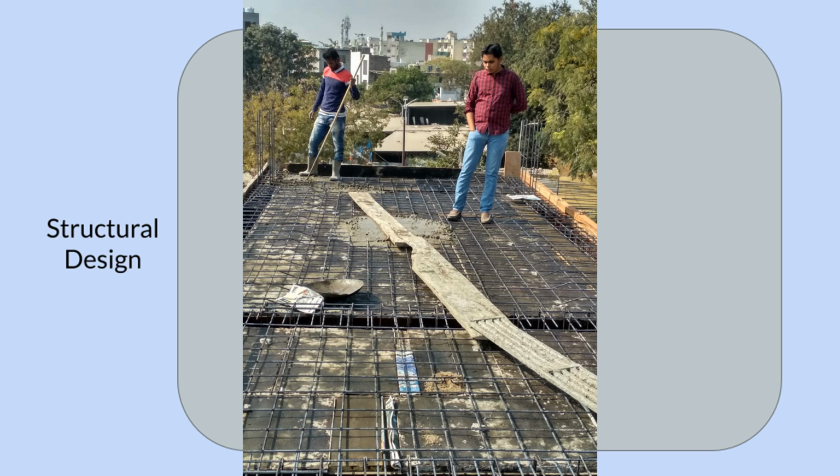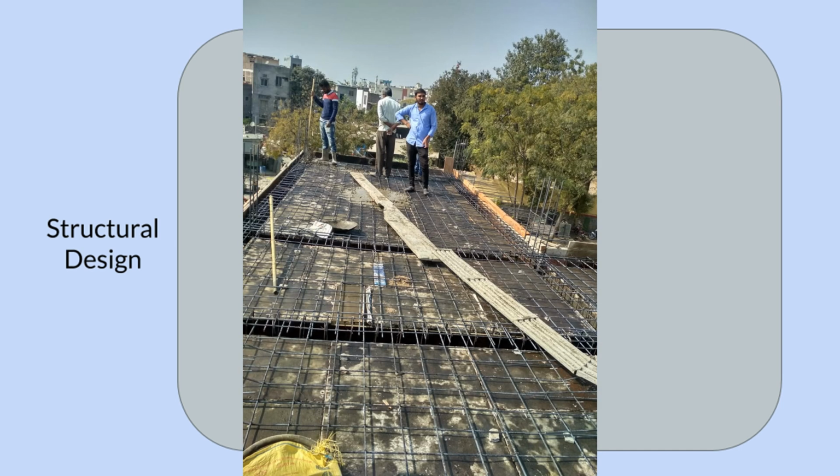A slab to beam connection usually appears simply supported, as bars are only resting on the beam bottom rebars and the top bent bars are resting on or continued up to the next span of the slab. But as they are cast monolithically, the joint is a partially fixed type because the slab cannot rotate independently.